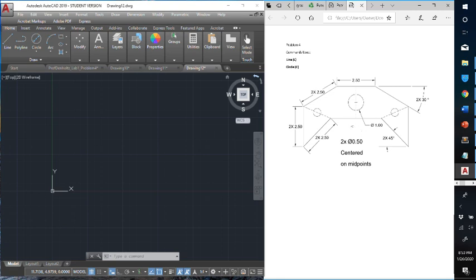I'm not going to. I'm just going to use the commands given over here, so basically lines and circles. I'm going to start by doing the exterior. And when I start the exterior, I'm going to start at either this corner or this corner. Now, the reason why is that we're not given this length. And so I'd rather start at one, go all the way around, and then when I get here, just connect it with a horizontal line. That prevents me from having to do any significant calculations to figure out the length. Then once I get there, I'm going to add in the circles.